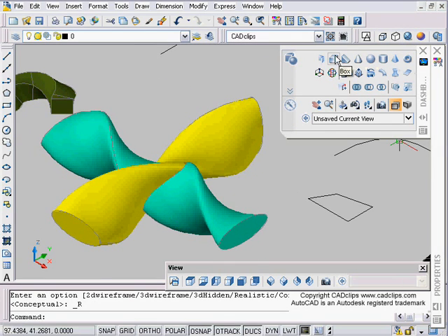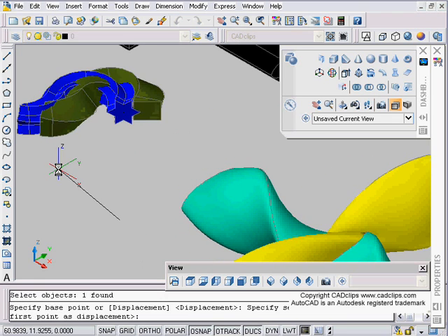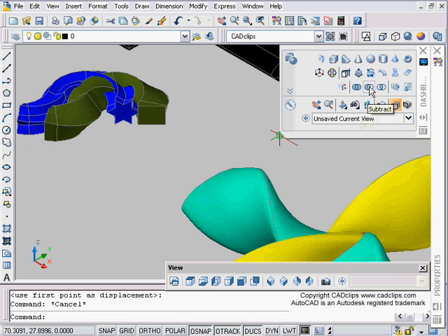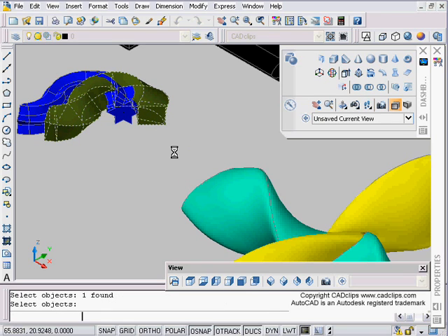Try it out, experiment, get creative, start to use all of these tools we've been talking about. Don't forget about our Boolean operations of intersect and subtract and union, which is where we can take these objects and start to blend them in with each other, and then maybe do a subtract from this, enter, this, and then it'll actually remove from that.